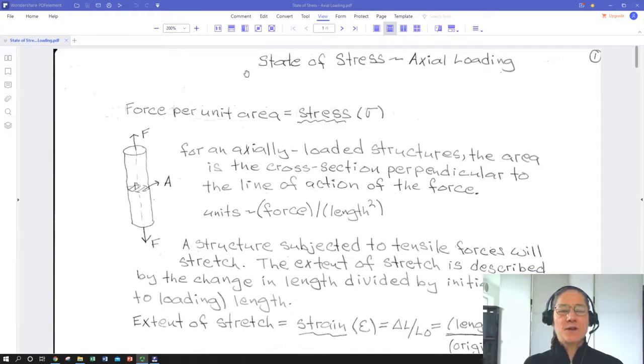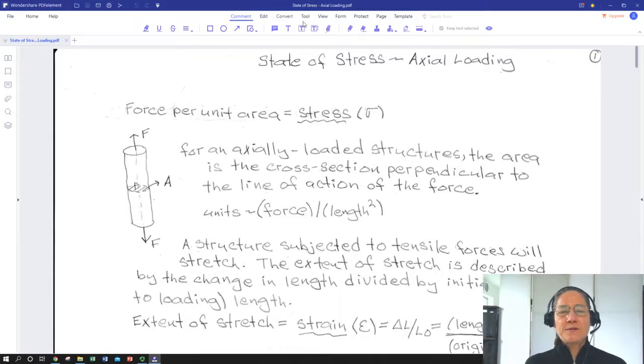But let's get started with a very important concept for mechanics of materials, and that is the concept of stress. And how is stress different than just force or load? To do that, we'll take a look at a really simple object that's being loaded, and that's a cylinder. With this cylinder, we've got a cross-sectional area of A, perpendicular to the cylinder's axis, and we're yanking on that cylinder with a force F. We have to apply it to both ends, otherwise it'll accelerate. It's in static equilibrium, and it's seeing a force along its axis of F.